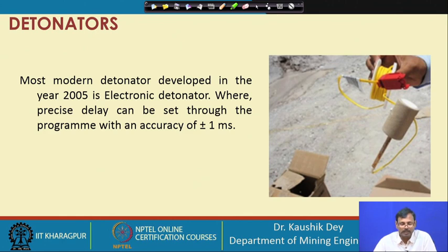The first reason is that it is a chemical material, and the manufacturing of that chemical inherently has some heterogeneity in its mixture. As the chemical does not have a consistent property, the heterogeneity is there. That is why the burning rate is different. So, the burning rate changes from day to day manufacturing of that chemical, and as those chemicals are used in the detonator, their delay timings, their burning timings become different, and that is why deviations are coming.